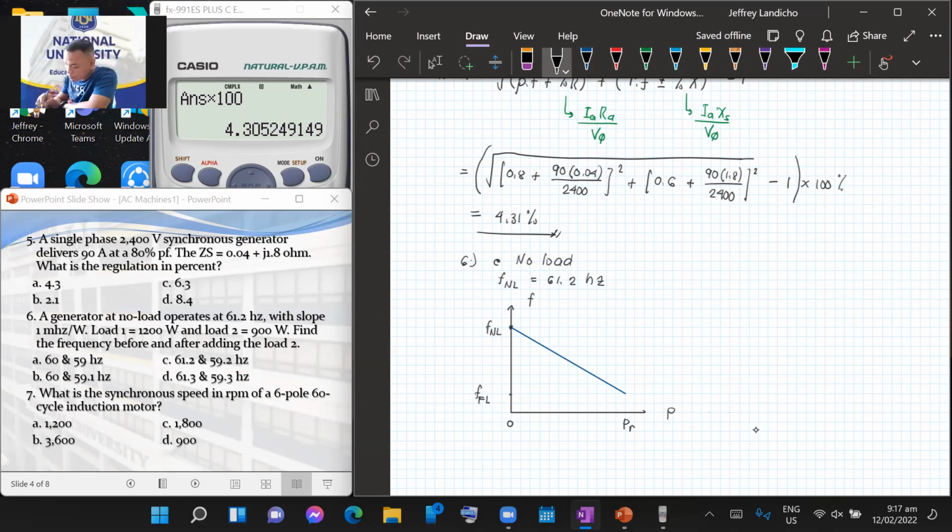So you now have the straight line characteristic. The slope of our line, when slanting to the left, should be negative. This slope represents the change in the given frequency per change in corresponding output power.